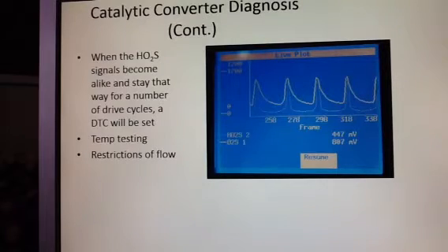We talked about our catalytic converters last week quite a bit and in the week prior. We're getting into this now where we're looking at our sweeps up and down. If we're looking at this on our scan tool and I see my post-oxygen sensor the same as my pre-oxygen sensor, we are seeing a problem. Our pre-oxygen sensors should be moving up and down. We should be seeing that 0 to 1 volt sweep or that 100 millivolt to 900 millivolt sweep, either way, one of those ranges. Now, also with that, we should see that post-oxygen sensor staying very, very steady.